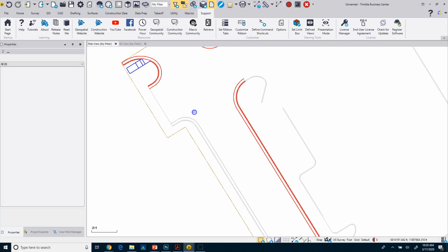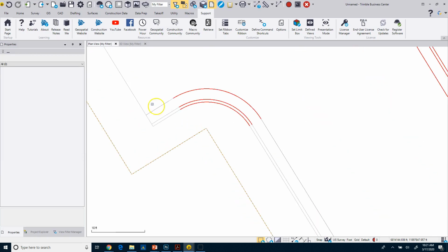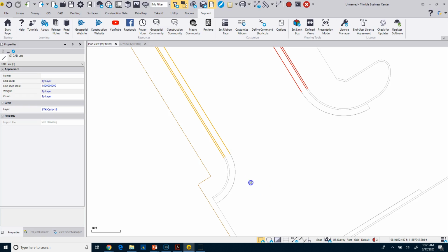And now what I can do is simply select those objects and Control 1, and it automatically relayers those. So again, I can select these objects and I can Control 1, come down here, Control 1, and quickly relayer these objects